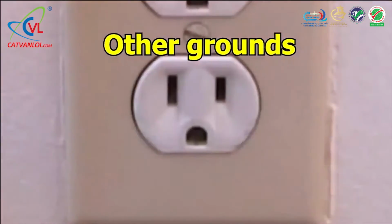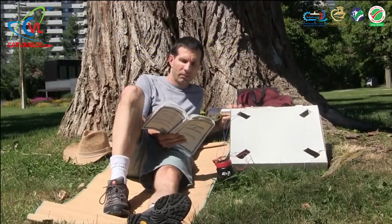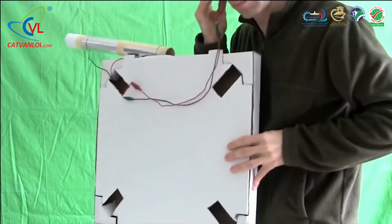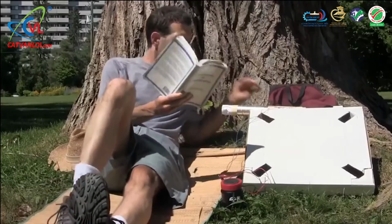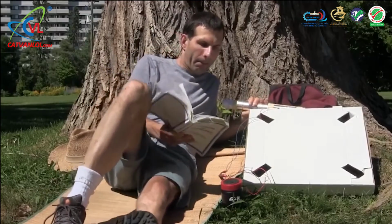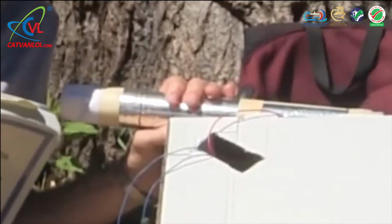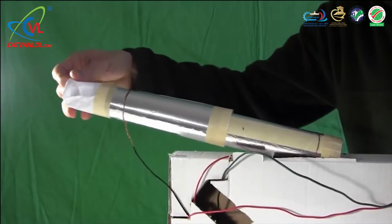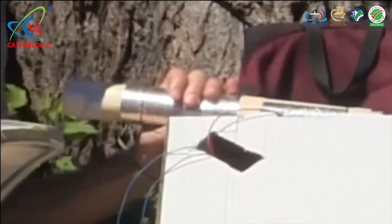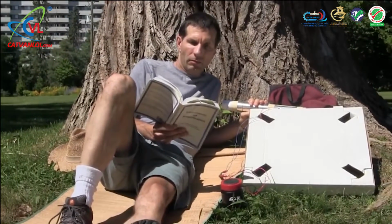Besides the ground hole in the power socket, you have to define the ground to use. If the current and voltage aren't too high that you get hurt, then your own body can sometimes act as an okay ground. The example where I've done that is with this portable pizza box crystal radio. It's portable because it doesn't need a ground to work, but it works better with one. And if you look closely here, you'll see my hand is on this capacitor plate. The capacitor is one aluminum foil cylinder that slides around another one, and with paper in between. Making a lot of skin contact with the outer cylinder lets it conduct charge to my hand and body.